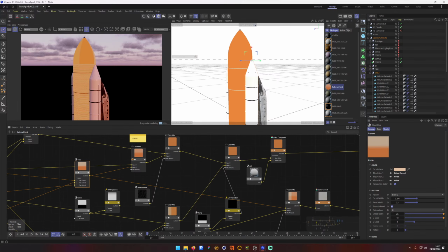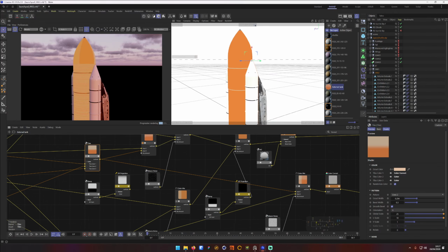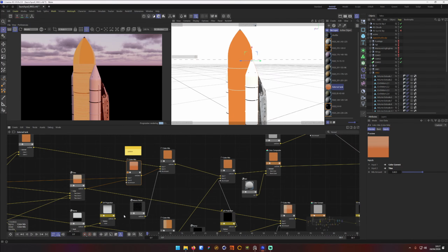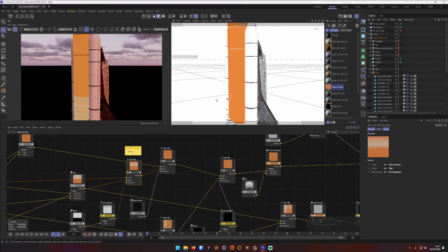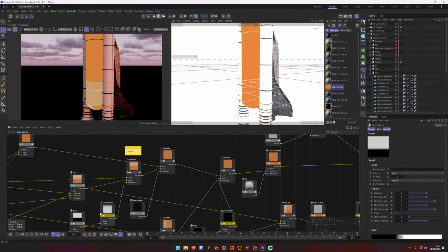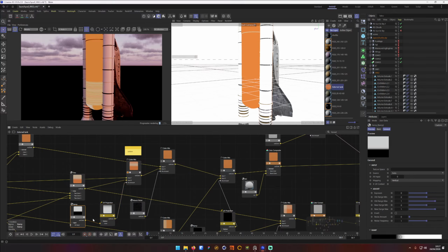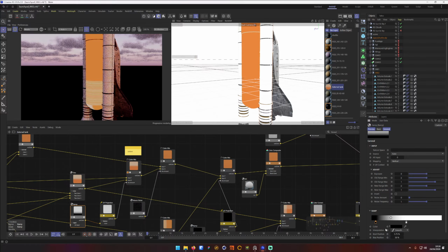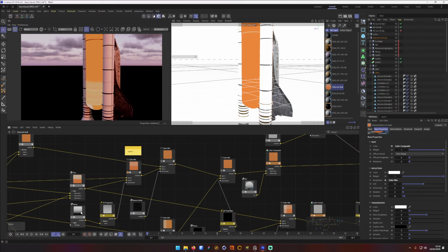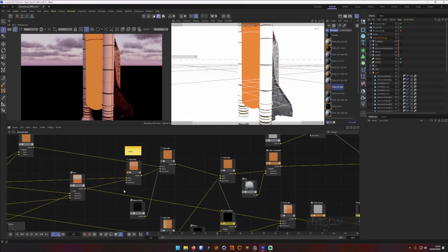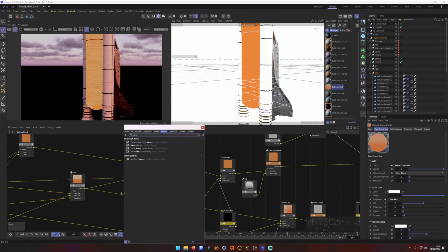But yeah, as is the way of not really thinking about what you're doing as you're doing it. So this colour mix is set to 50%. Let's look at our UV projection. That's going to break it. Cool. So there's the issue. The UV projection is set to planar world, and flipped on half. So now it's vertically projected. That's cool. And then the problem is inside this ramp. So let's have a quick look. Let's eyeball it. That's weird. Alright, so what I'm going to do then is delete this ramp, delete this UV projection, and create a new ramp.